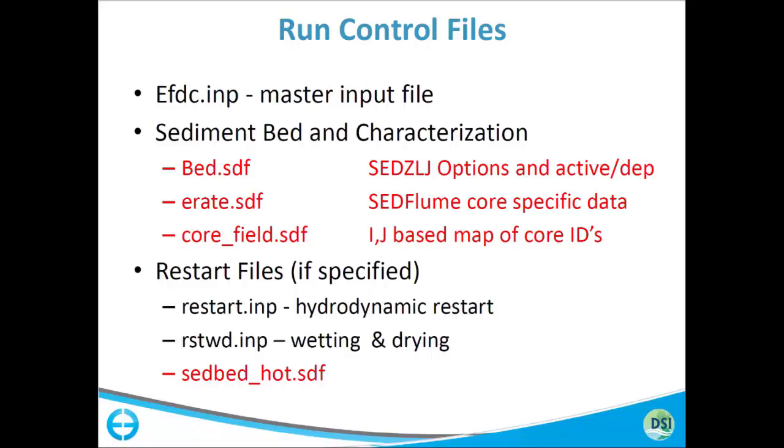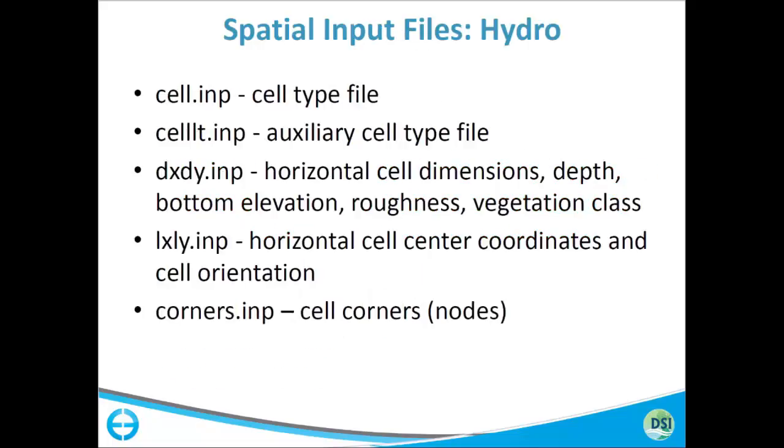Let's see here. Corners.inp, the rest of this, all these files are standard EFDC files. This is an EFDC Plus file. We use it a couple of different ways. Number one is we've calculated the nodal coordinate value at all the connections around a cell.